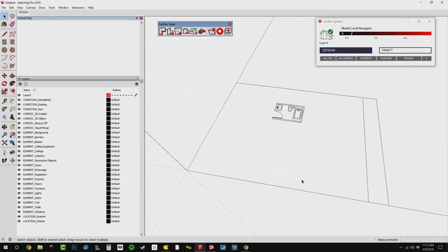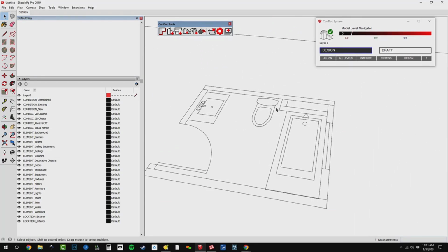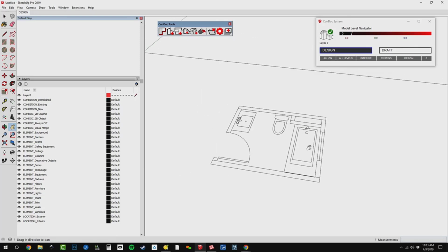All right. Now, in order to scale this drawing, we need to do a reality check. When I measure this from here to here, see, it's like 1/8 of an inch. That's no good. That's not what we want. All right. So we need to make this 4.5 inches. These walls are all 4.5 inches.